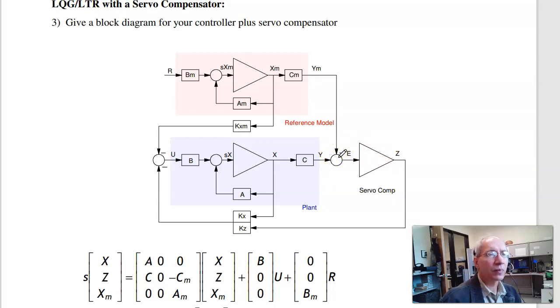Now do the same thing. I am going to use LQR techniques to find the output to be z in this case. That's kind of a quirk of servo compensators. The weighting is actually on the state you don't care about, z, and ignore the state that you do care about, e. Basically, the math is dumb. It thinks this is the output, y, and it thinks this is y dot. So by weighting the error, I'm actually weighting y dot, meaning get there slowly. By weighting z, it says get there quickly, so to steady state. But anyway, we'll get to that in a sec.